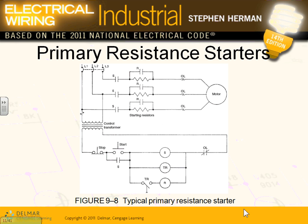The other thing, guys, is starting a motor. When you start a motor, the worst thing is the inrush. What's wrong with the inrush? Two things. We always call them electrical stress and mechanical stress. Electrical stress means you have a voltage drop. When you start the motors, the lights will dim because a huge amount of current gets sucked by multiple motors. That's bad. That's electrical stress in your system.